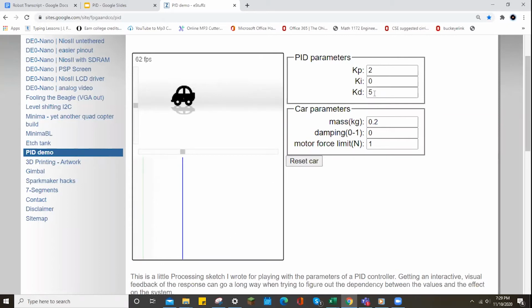And that's what the D controller does. When you're getting from point A to point B using the proportional controller, trying as fast as you can to reduce the error of position, KD helps dampen the extra error that can be caused by trying to solve the error, by making sure that when you're coming close to the error becoming 0, you slow down the output as well, so you don't go way too far past it.